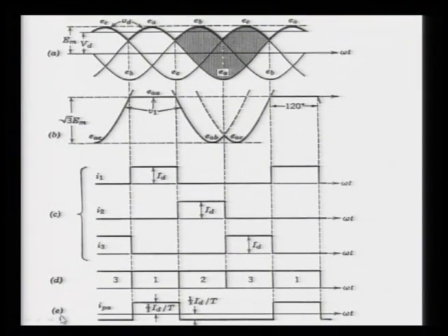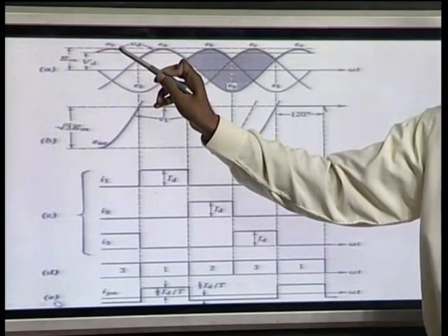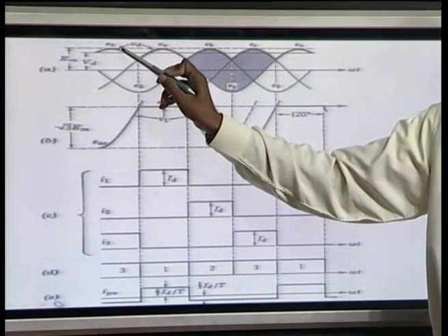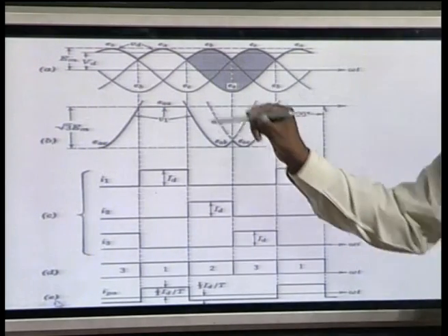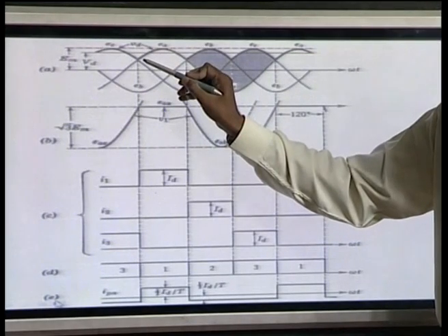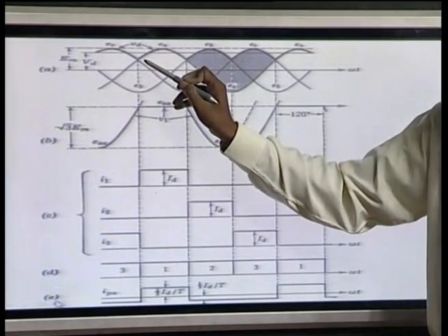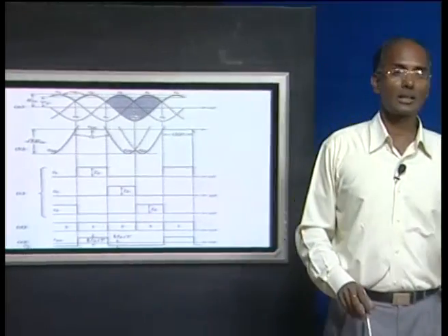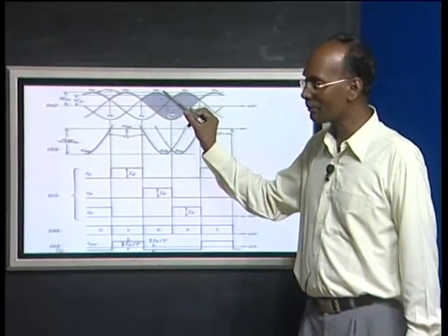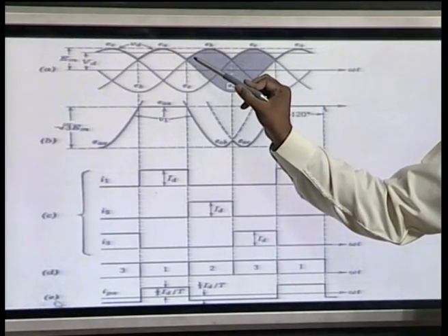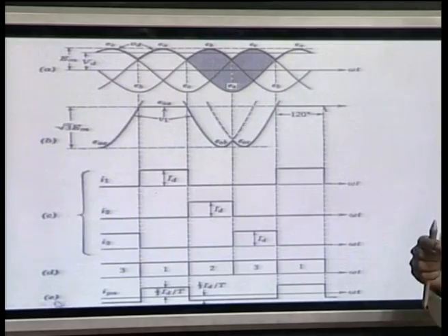Now, here as I said, we are taking the 0 axis, where EC is the output voltage, which means valve 3 is conducting. So your current was flowing from EAC to neutral in that previous diagram. Now at this point EA becomes positive compared to EC, so EA minus EC here is 0, and this EAC is called the commutation voltage of valve 1. Similarly, the commutation voltage of valve 2 is EB minus EA, which is going to be positive.